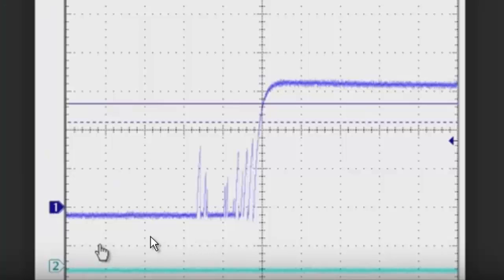And that issue is called bouncing. And this is the signal. When the button is pressed, the signal gets high. These are the cycles between the lines. What happens if you touch the wires? Then there is noise in the current and you get a bounce between 0 and 5 volts. And sometimes the Arduino reads a difference and thinks it's high, and then it starts burning the LED.